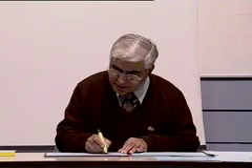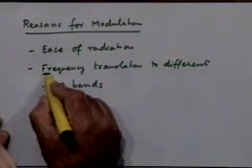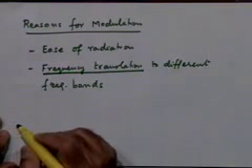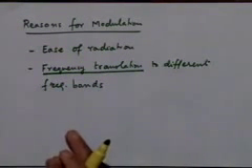Yes, please. So is modulation only increasing the bandwidth? In general, that's not the purpose of modulation. If the bandwidth increase happens in a particular kind of modulation, that is incidental. That is not desired, not necessarily required. All that we want is not increasing the bandwidth. We are modifying the location of the spectrum. Please remember, bandwidth and location are different issues.